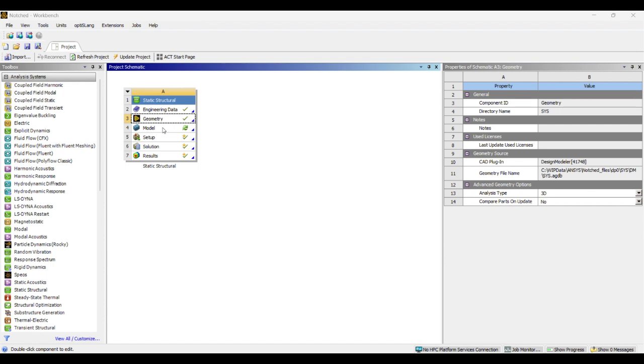And sometimes it can be computationally expensive to refine the whole mesh in the model. So what you can do, and what I'll show you, is that you can create a submodel that has a finer mesh so that you can achieve stress convergence in the model.